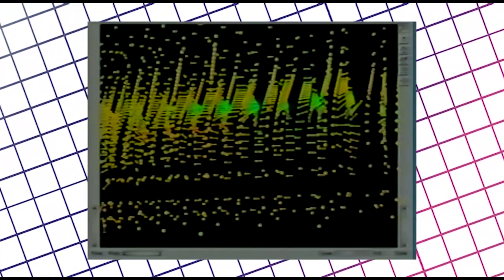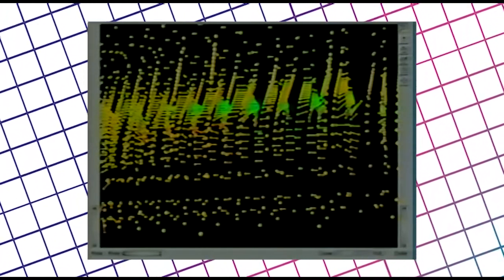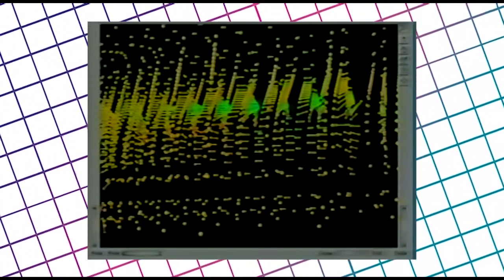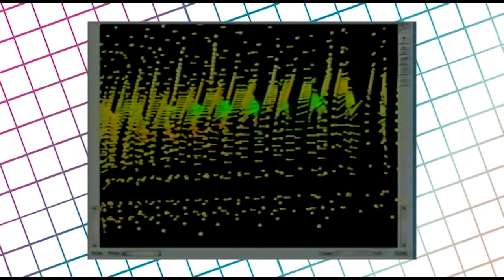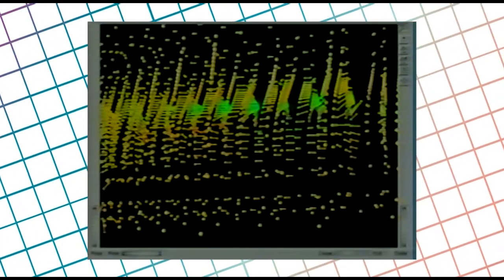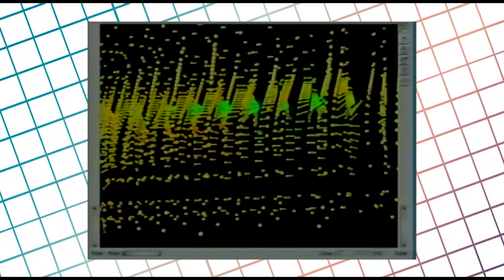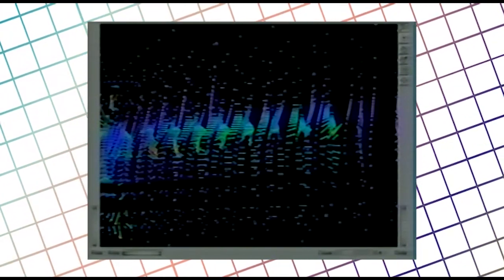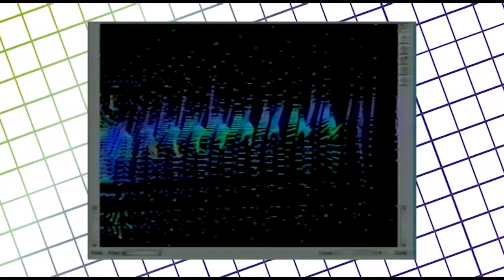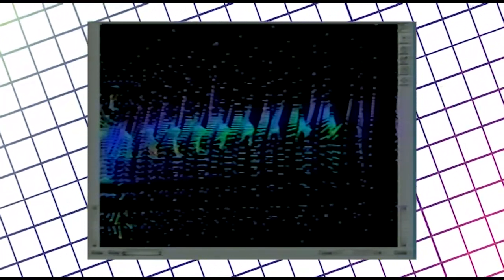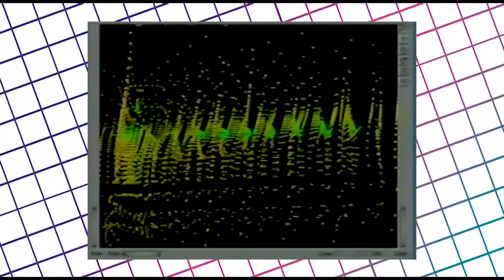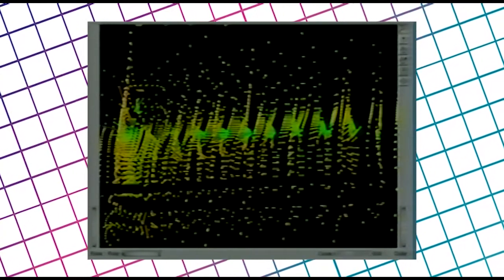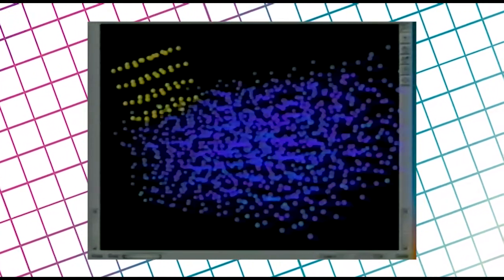Smith's fountain effect simulations find time sequences of 3D vector and scalar fields that may hold small vortices obscured by large steady-state flows. With GlyphMaker, we can set up compound sphere and vector glyphs with, for example, momentum bound to the vectors, pressure bound to the sphere color, and temperature bound to the vector color. Thus, we can study the correlation between variables and also conditionally isolate localized vorticity so that it is prominently displayed. Extensions that we are now working on will also allow simultaneous binding and display of streamlines, particle traces, and other fluid flow representations, along with the glyphs shown here.